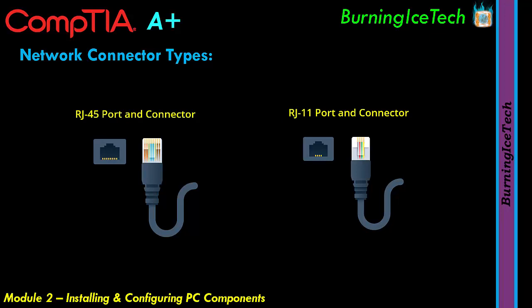So yeah. Now on the right hand side, we've got an RJ11. That's the old conventional telephone lines. Many countries don't even have these anymore, but if you have a country that's using the old telephone lines, that is a telephone line connector. It's got about 4 little wires in there, possibly 4. Normally, in most cases, it's not going to actually be 4 wires. It's got 4 connectors, where the RJ45 on the left has got 8 connectors. 8 connectors, guaranteed 8 wires. Right hand side, 4 connectors, but not necessarily 4 wires.